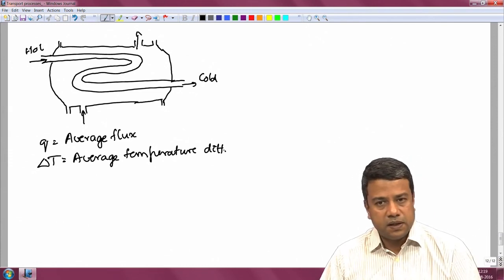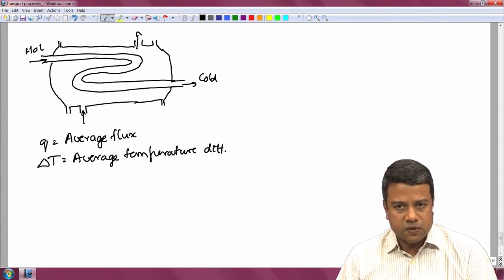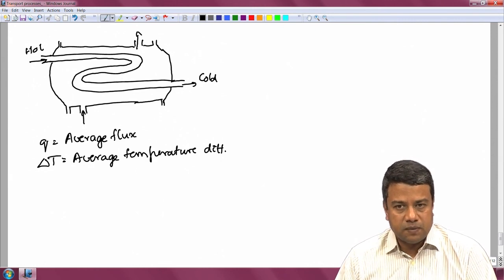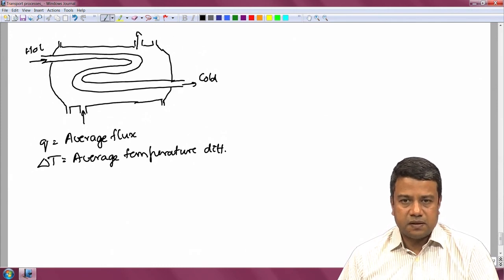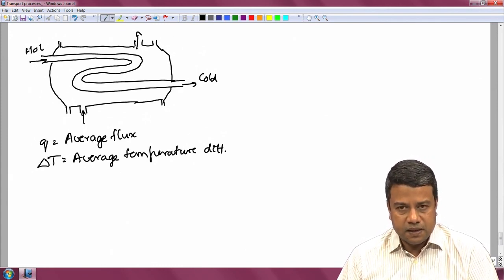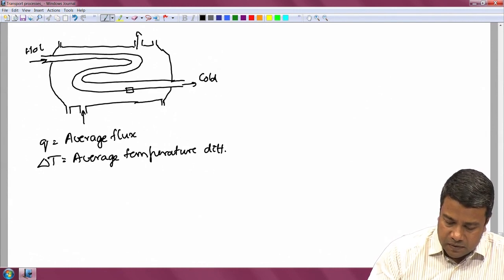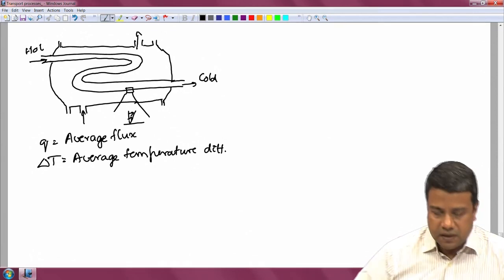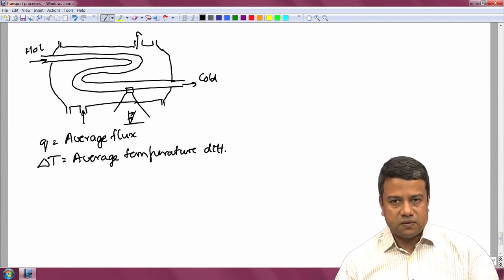It is going to be a function of the average temperature difference between the shell side and the tube side. But it is more than that. It also depends upon other quantities. It depends upon the thermal properties of the fluid, the thermal conductivity, the specific heat. In addition, the heat that is being transferred is being swept into the tube due to the fluid flow itself. And so, if I look at a differential volume close to the surface, there is fluid that is flowing across the surface, carrying the heat with it as it flows, and that has to diffuse through the surface to the other side.